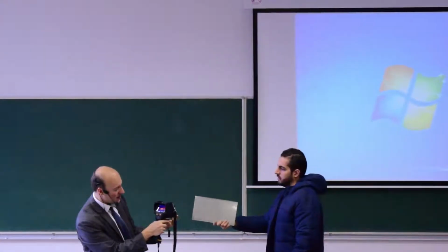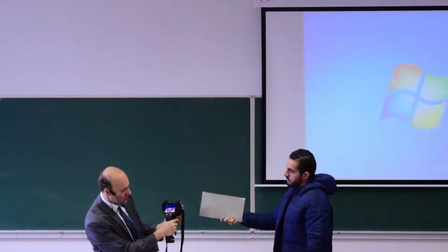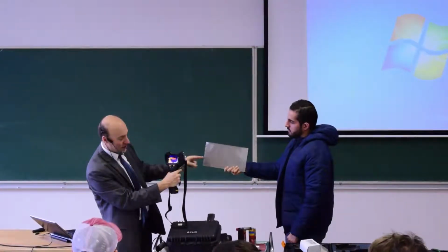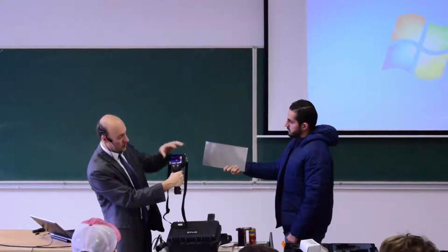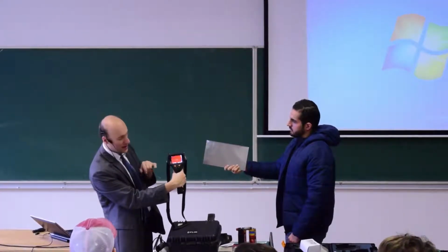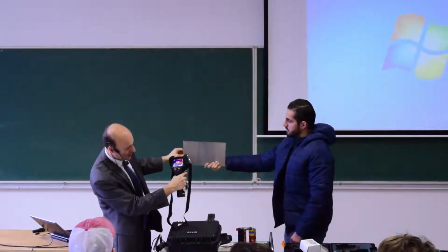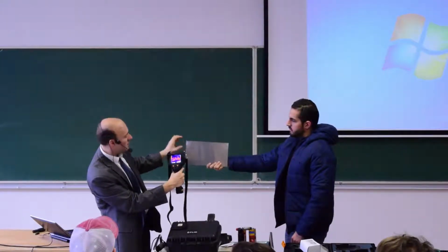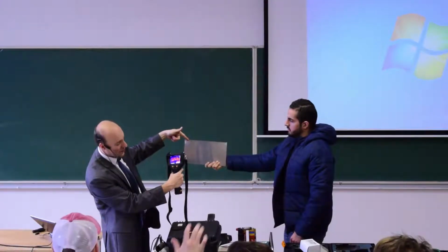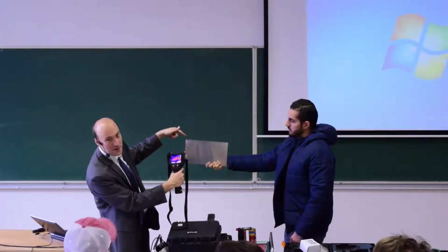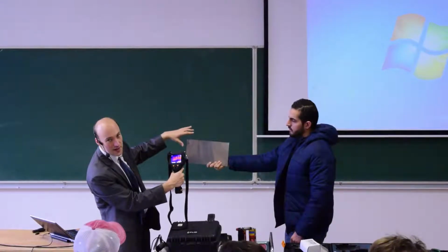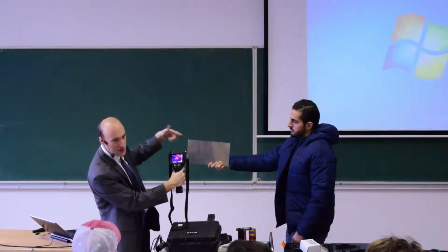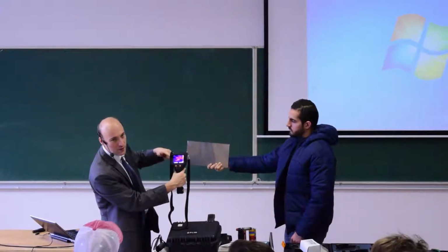What you should see here now is the reflection of you in the metallic sheet. Do you see it here? Can you move it? Yeah. So you see, this is the reflection of you. This is the reason why you have low emissivity here. So we have low emissivity. Most of the energy that is received from you is getting reflected from the metal.